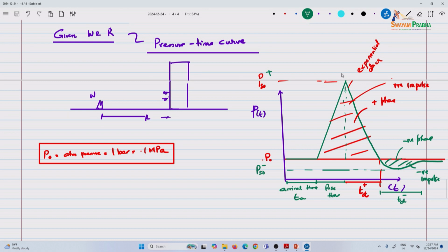The positive duration is considered to be from the peak to down. Usually the rise time is probably a tenth or a hundredth of the positive duration. Rise time comes into play when your pressures are low, and even then you don't consider it as a rise time, because then it's more of the deflagration situations. Most explosives, at least, I've not seen where a rise time affects results so much. So it's even on the order of a thousandth of a millisecond, right? Yeah, you're right.